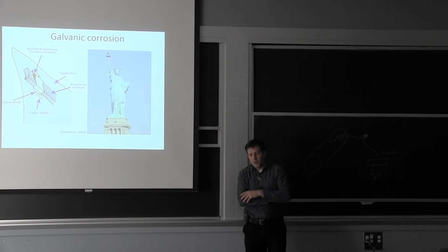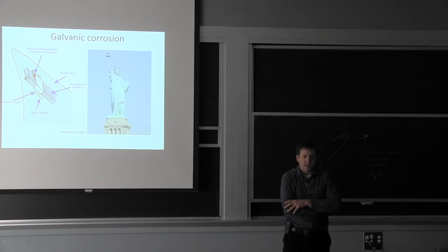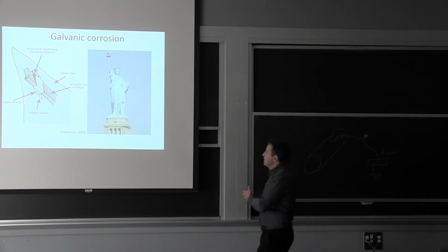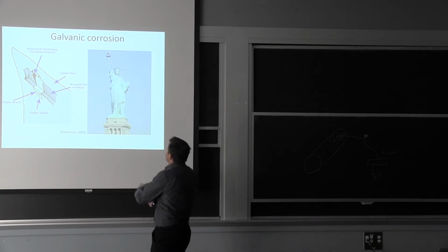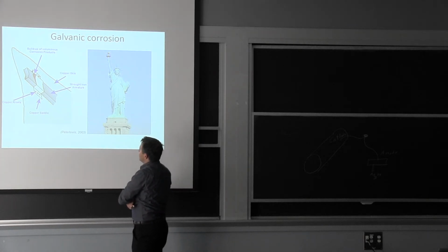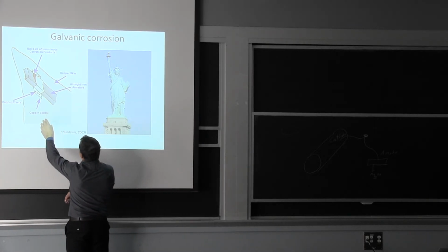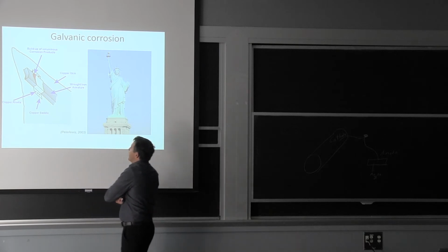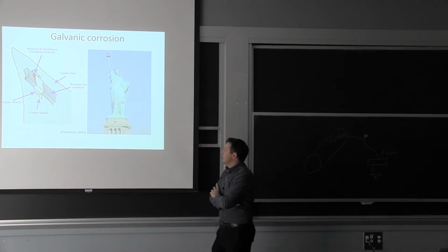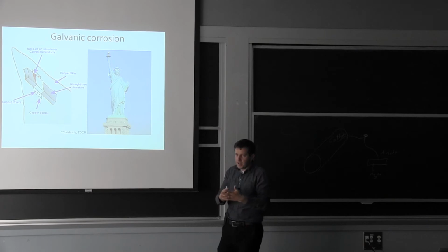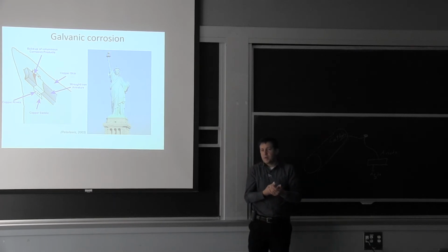Now, there's a lot of things in terms of galvanic corrosion that have to do with differential sizes. So the biggest issue here, if you have the big copper structure, then you have the little clamps and you have the armature right at that interface. Those rivets that are really making the connection, they're very small. So if it was all connected and bonded through the whole length, you wouldn't have a localized effect, but it's the proximity that makes things more terrible.